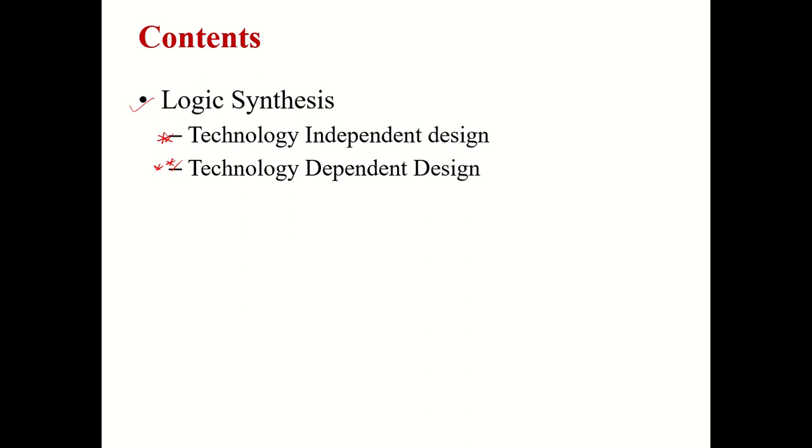In this way we'll map it, based on different industry-standard platforms like Xilinx or Altera, or Synopsys, Mentor. So we take the technology-independent design to some platform where technologies have been defined, from which we can get the transistor-level design.